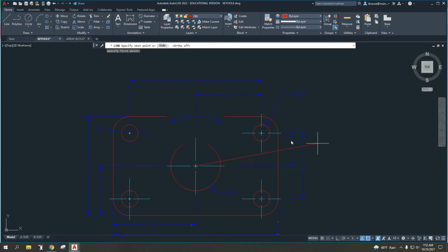Okay, so if we want a 60-degree spread here and 90 is vertical, I'm going to want to draw a line for the right-hand side at 90 minus 30, which is 60 on this side. However, on this side, what's 90 plus 30? That's 120. Okay. So you have to understand the angles first, depending upon what angle you're going to want on the drawing. So 60-degree spread, separated in this case by the vertical 90-degree orientation. 30 degrees before 90 is 60. 30 degrees after 90 is 120.